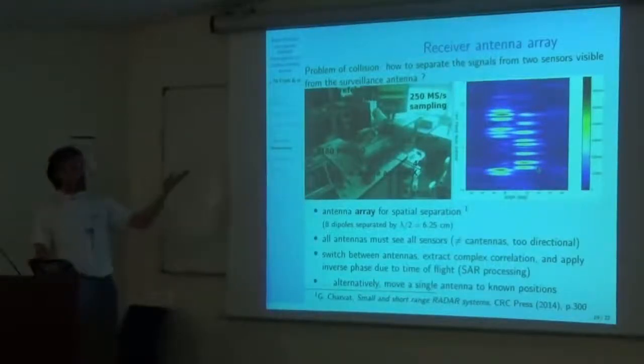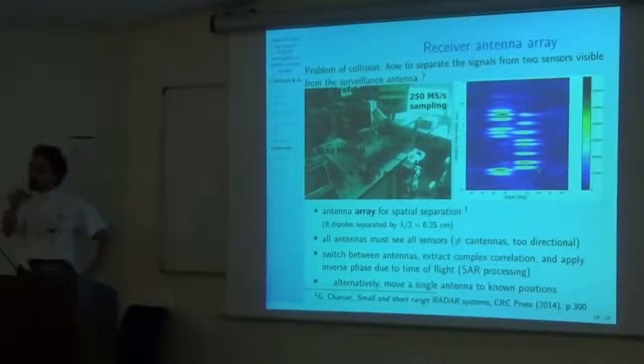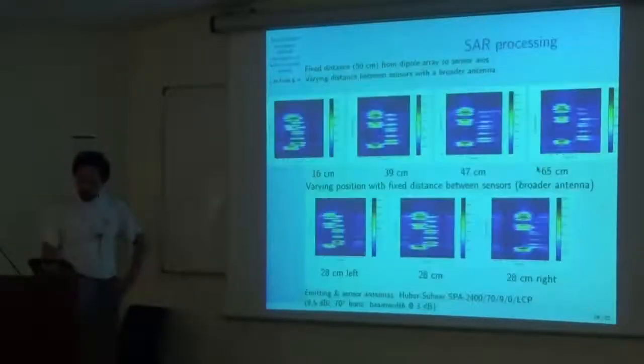So basically what I wanted to show you here is that passive radar needs a dual channel oscilloscope, GNU Radio with a Fourier transform analysis to get the correlation computed, and then direct signal interference removal. This at the moment is still done offline using MATLAB or Octave. And then you can extend the strategy of passive radar to phased arrays by taking direction of arrival measurements. So that's just to get you interested in passive radar and how to implement passive radar using GNU Radio.